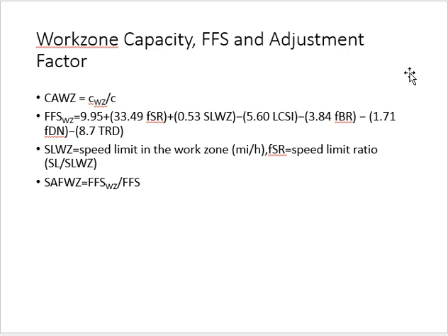You have to count, you have to look at your segment in the map. So you open the map, okay, Google map or whatever map, and then you look at your segment. Let's say this is my segment. From my segment, I'll draw a line 3 mile forward, then come back, draw another line 3 mile backward. 3 mile forward, 3 mile back. Total? 6. Okay. In these 6 miles, I'll count how many ramps I have. Now take this number, divide by 6. This will give me TRD.